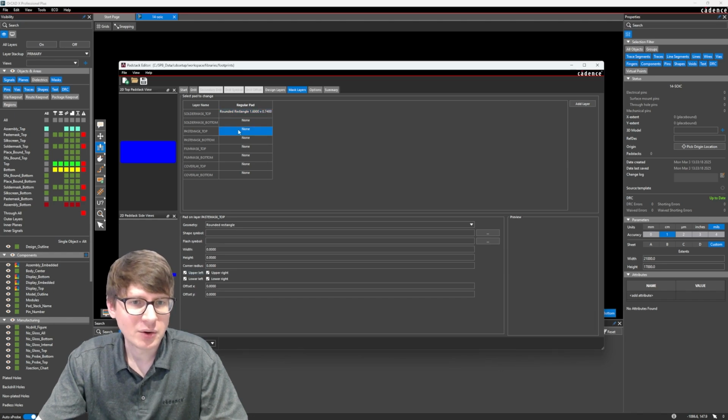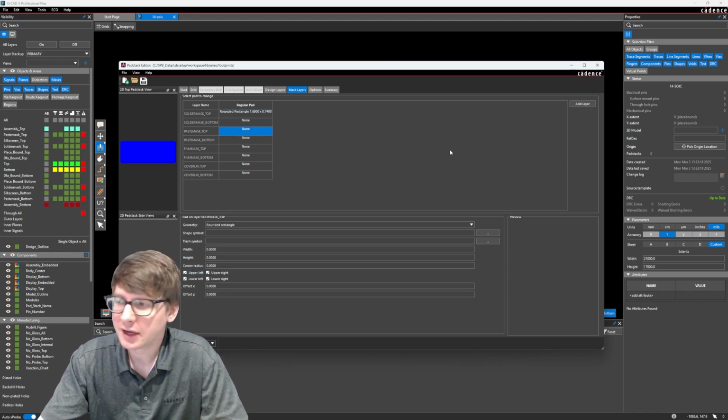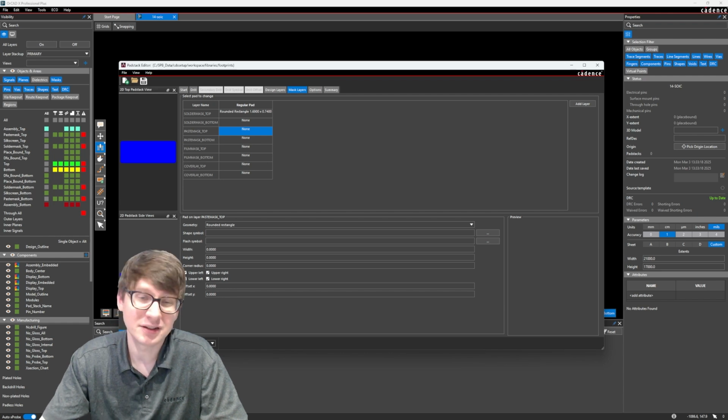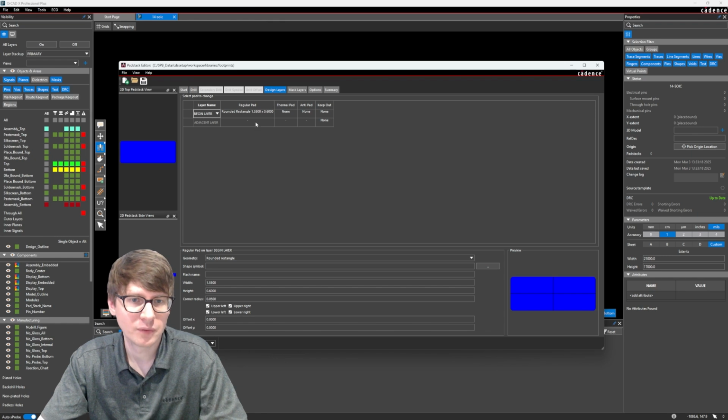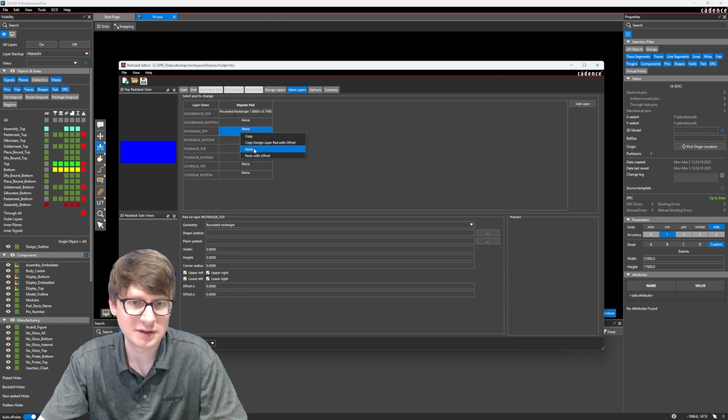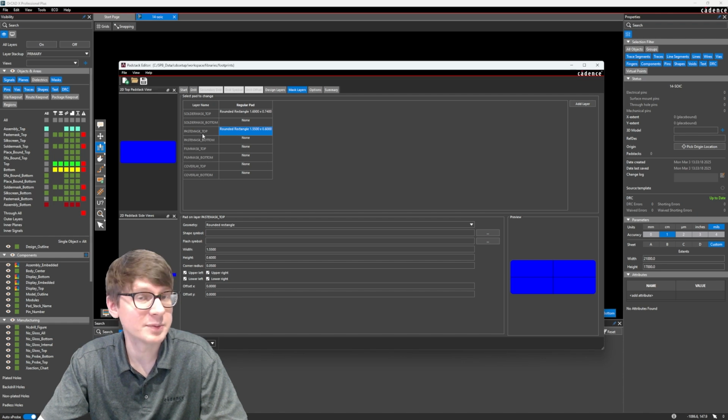And then finally, let's go ahead and add a paste mask layer. Looking at the datasheet, it looks to be exactly the same size as our original pad. So you can either rewrite this information here, or if we go back to our design layer, copy this and paste it in our paste mask top layer.